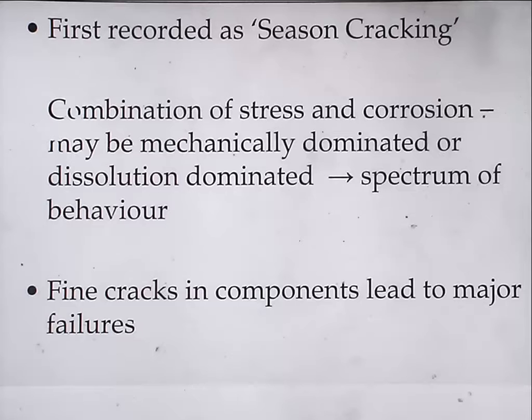There's been a lot of work done on stress corrosion cracking, and there's several mechanisms at play, and they all overlap. So you get a sort of spectrum of mechanisms that run from mechanically dominated, i.e. the stress is the most important factor, to dissolution dominated, where the stresses are low and the corrosion is the fastest component of the combined action to give you cracking.